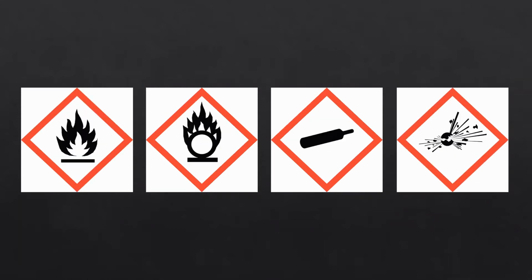These pictograms are for the physical hazards you may encounter with the products that you are using. The first one is the flammable symbol. Essentially these are for anything that will cause a flame and may cause fire, pyrophorics, self-heating. Some of these may need an ignition source. Some of them may ignite on their own, but in any case, a fire is the potential for these.